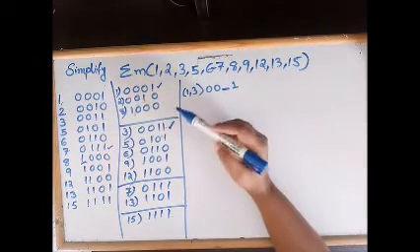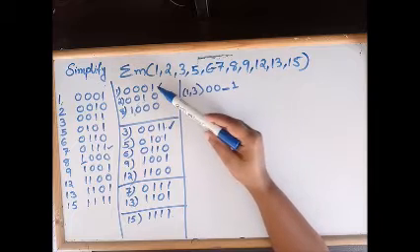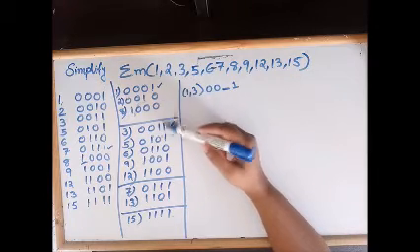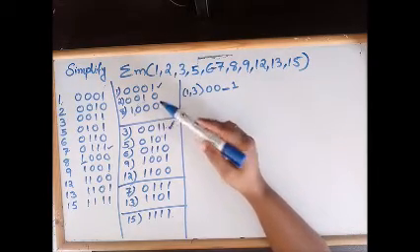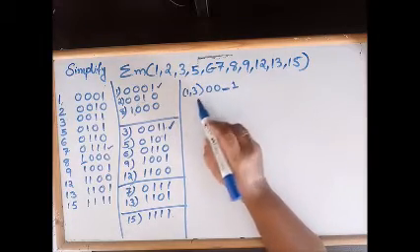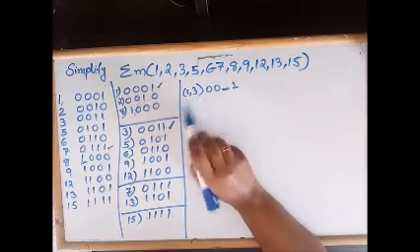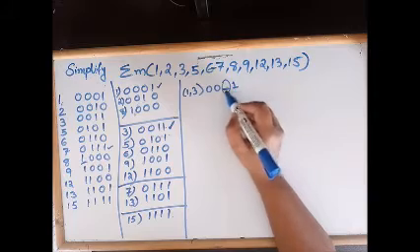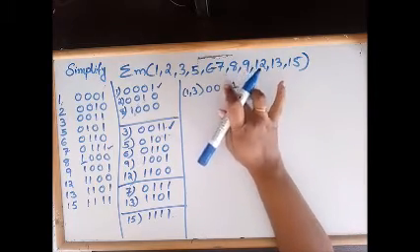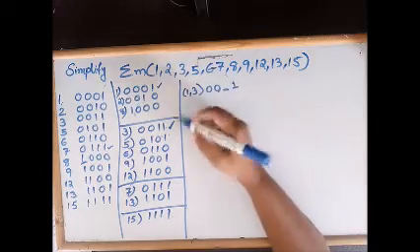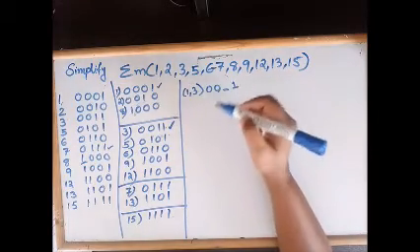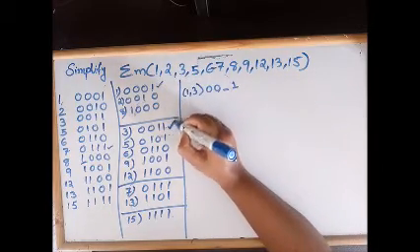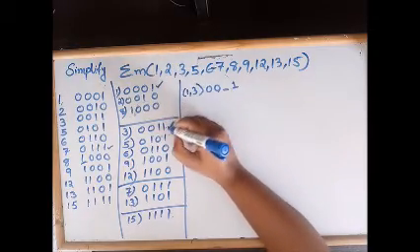So what is the procedure? The procedure is I compare the first term in the first group and first term in the second group and identify the bit change. If there is only a single bit change, I can combine these two, that is I can combine 1 and 3 since there exists only a single bit change, and bit change is at this position. So I am just placing a dash symbol here. Okay. So similarly, I need to perform this comparison element by element wise, and when you combine two terms, I need to put a tick mark. Okay, those combined terms, just put a tick mark.